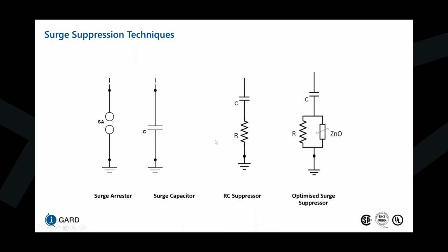With the addition of a resistor as an RC suppressor, we can reduce the wavefront magnitudes to a value that we dictate, and that way we can match the impedance so that we can reduce this doubling effect of these transients from escalating to higher points and reduce the restriking capability.